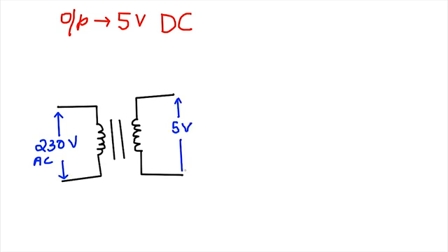However, I shall use a transformer of 12V as output voltage. Why? Well, I'll get to this point later. So a step-down transformer with 12V rating is what we will be using right now. If you have any previous experience in electronics, you may know a transformer's input and output are both AC voltages. So next step is to convert this 12V AC signal to DC.